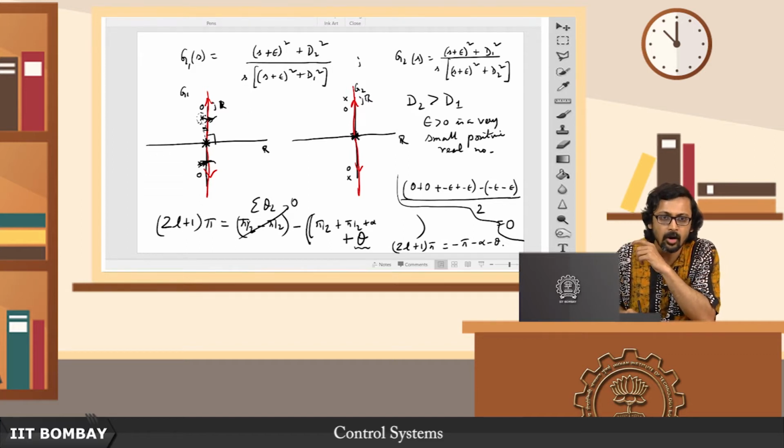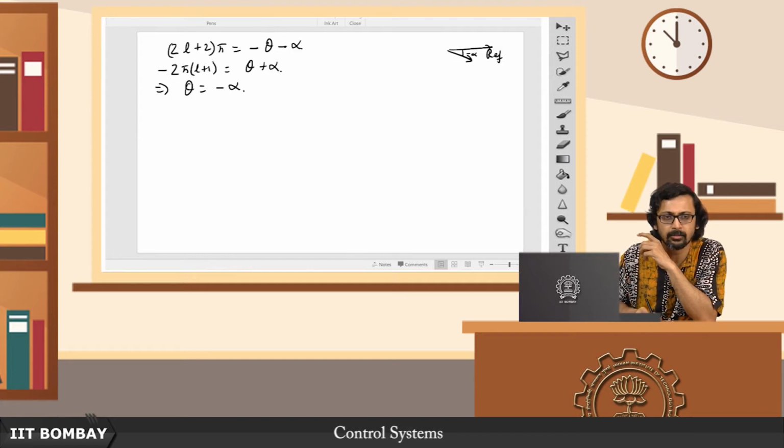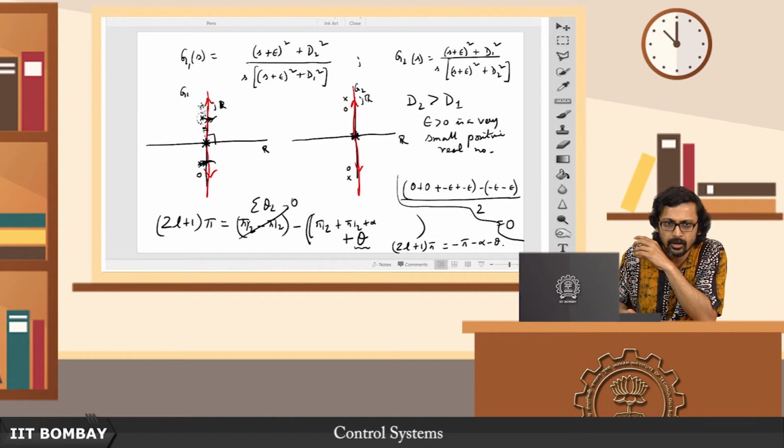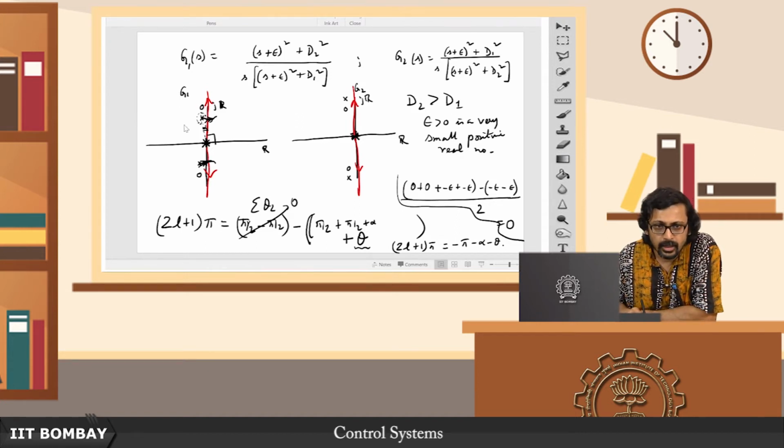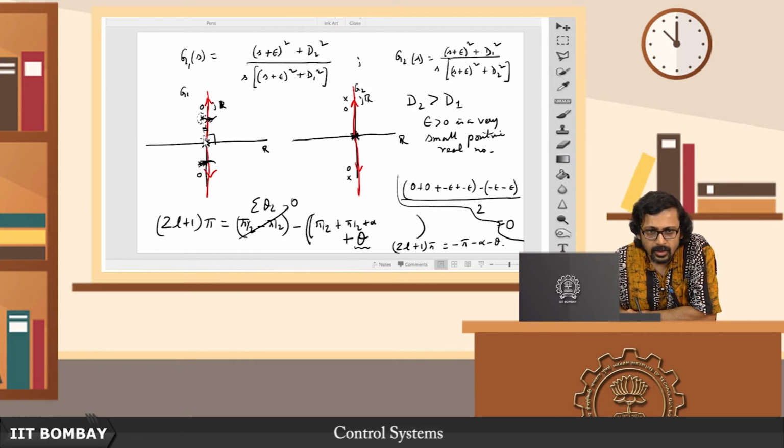Yeah. And now you apply the same principle around this 0 here, okay. If you apply it around this 0 here, what is the angle of arrival and departure? Let us account for the angles. So again this is going to be some pi plus beta, where beta is a very small angle given by tan inverse epsilon by d2, so that is going to be beta, right, very